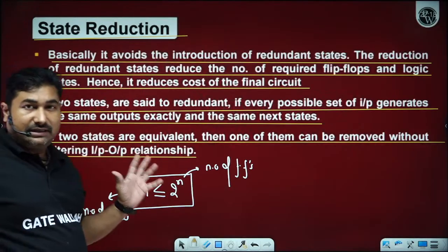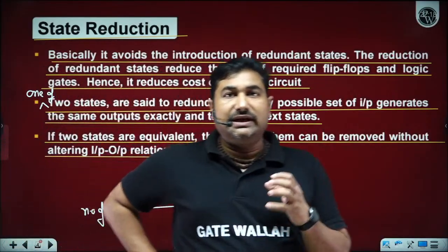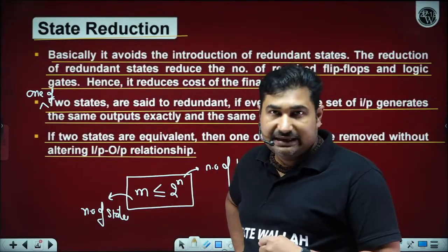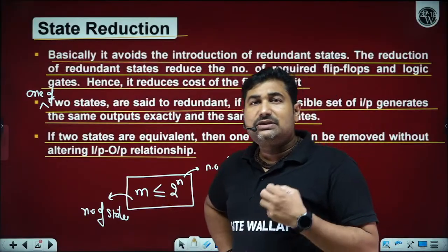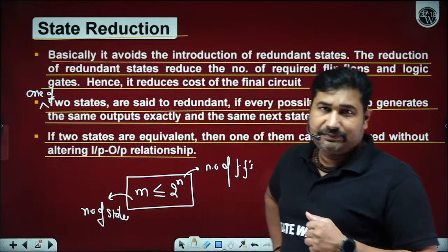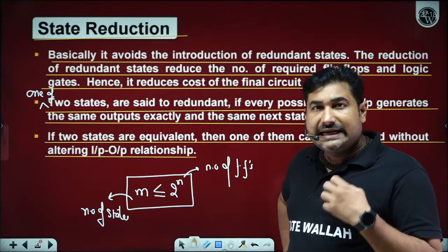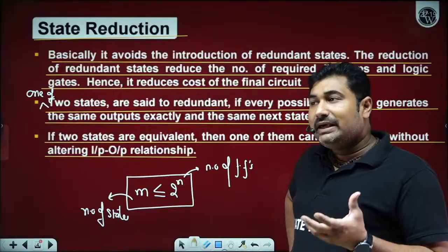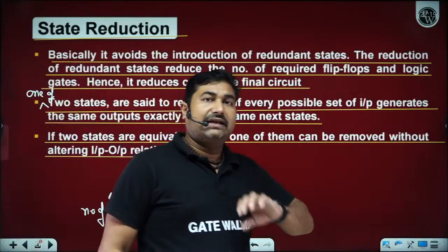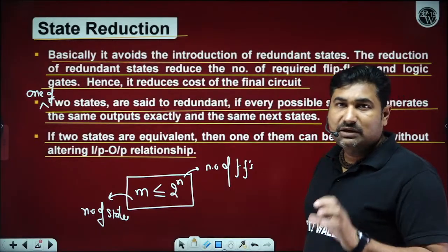What is state reduction? State reduction means, whenever a user asks a designer to design any desired sequential circuit, there is a possibility the user unintentionally gives more than the same situation to the designer. So the designer will examine all the situations through a state table and then make a reduced state diagram. With that reduced state diagram, the cost of the circuitry will be lower because we may reduce the number of flip-flops and logic gates.